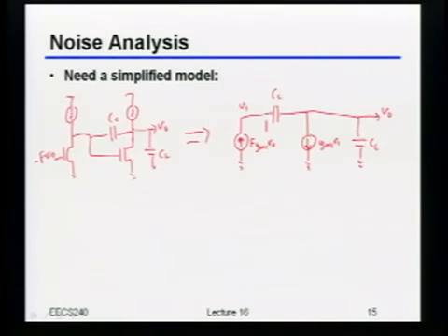The DC gain times CC? Yeah, basically. You sort of learned the Miller approximation, where you split that cap onto the two sides. I'm going to do something very similar. I'm going to assume that the feedback is essentially unilateral, so I don't want to deal with a feed-forward zero. The way I'm going to do that is something like the following.